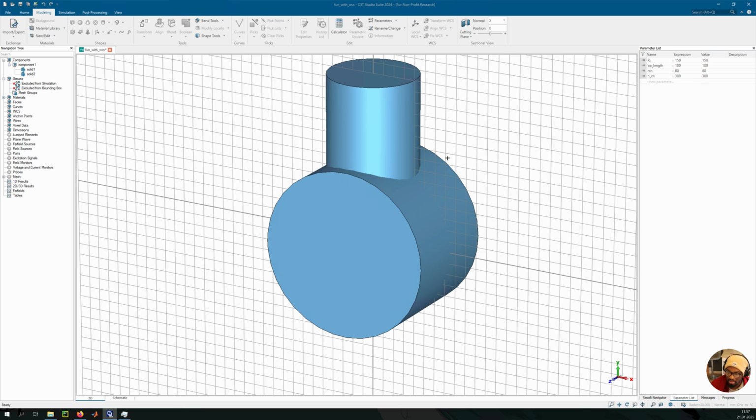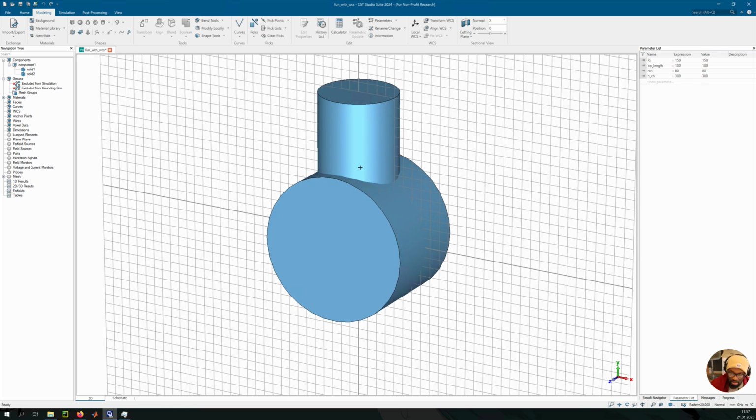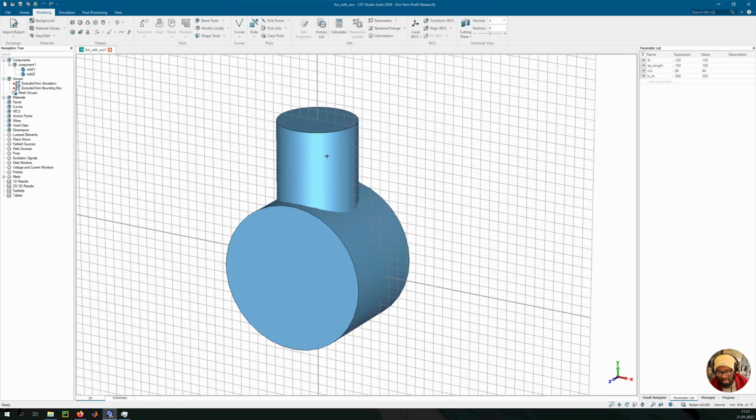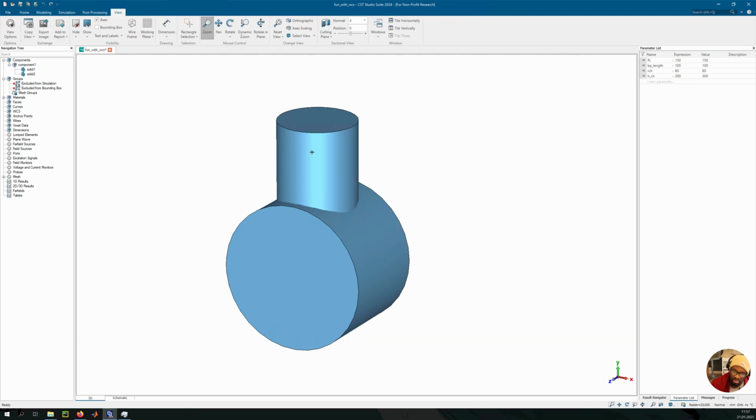Apply to all, no. So I could of course boolean this, but I usually leave all the boolean operations and all the edge operations, which is like chamfering or rounding the edges, for the last. So that's the last step I usually take. Otherwise, it sometimes causes problems building the model. So that's also something that you have to keep in mind.